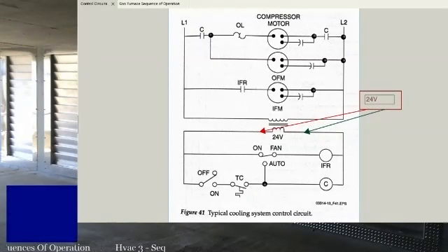Check for those things, fuses, all the basic stuff first. It seems like common sense, but especially if you're in the heat of trying to figure something out and something just doesn't make sense, whatever the case may be, a lot of times you'll be missing that first thing. Is your wire actually in good condition? You'll have a system that you go to turn on and it'll all run for a split second and then stop and everything looks good, and it could be a crappy wire, something like that. So if everything just seems out of whack, start with those basic things first.